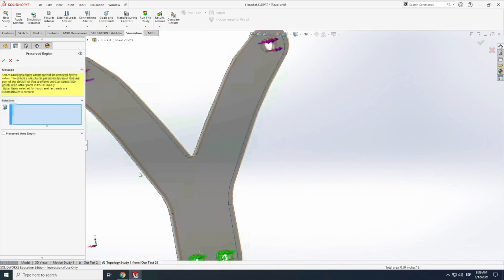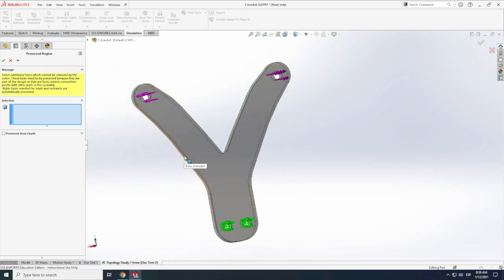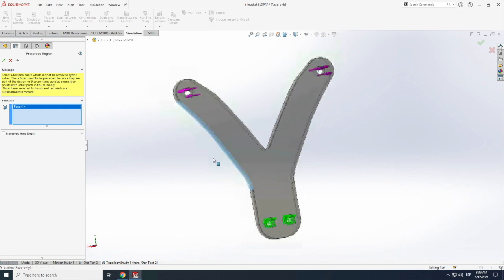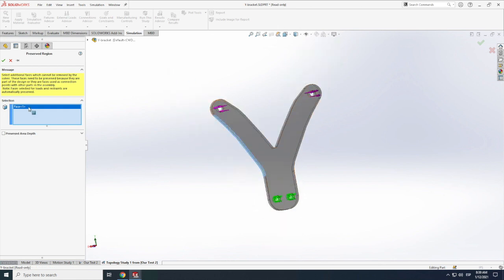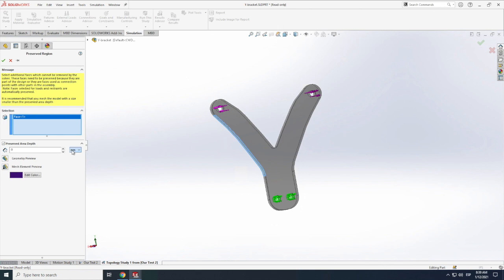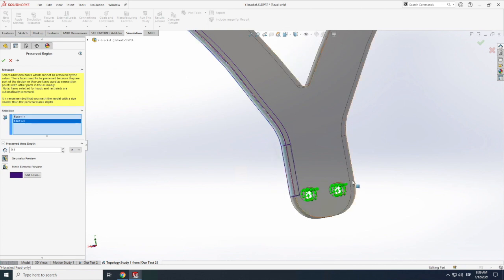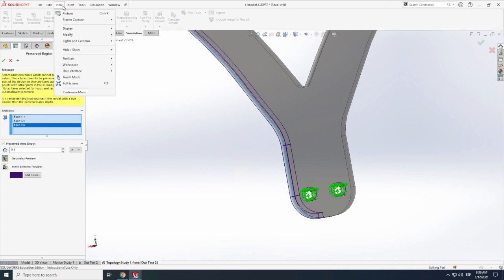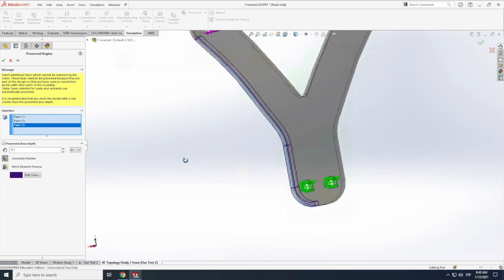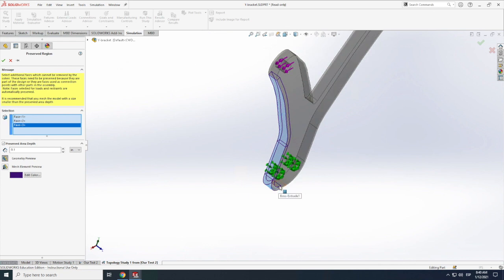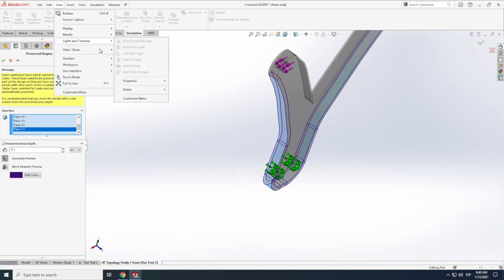Okay, I'm going to choose, there we go, the boss extrude, so just like this boundary in here. Let me see if it actually selected. Let's click 0.1 and the geometry preview. Oh, it only, so we would need to select all of these faces. We need to go all around, so let's do that real quick. For instance, let's say that you actually need the shape of this thing to stay the same. You don't want at least the boundary of the shape to change to some extent.